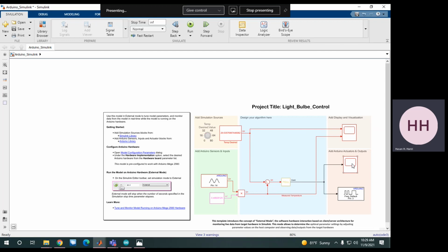Here we are monitoring our signal, and we are sensing our sensor on this side. As you can see, it's an analog input. We are sensing it, and here I'm multiplying it by a certain value or factor. I will tell you more about it. And here we can control our system or desired temperature in real time.